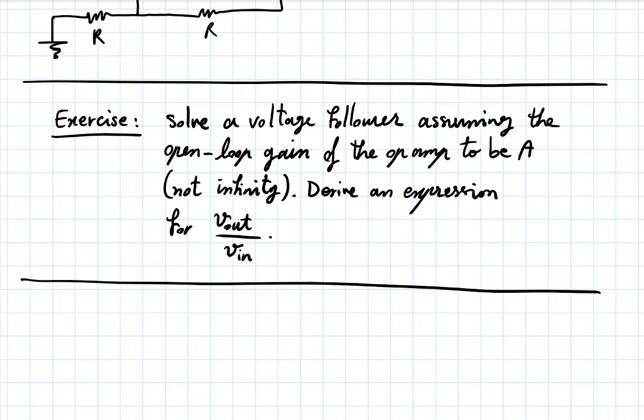There's also something called the input voltage offset. Let's say you build an op-amp circuit and assume that an input voltage of 0 will produce an output voltage of 0. But in practice, you build it and it doesn't. This is because of the non-idealities of the op-amp. So when you buy an op-amp, and you will see this in your lab, there will be some extra pins that normally allow you to compensate for some of these.